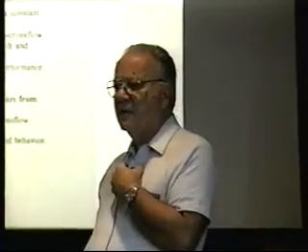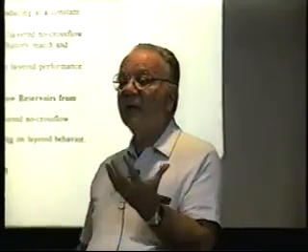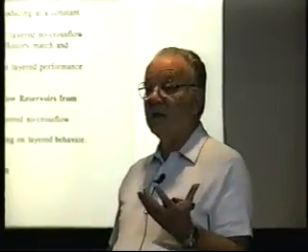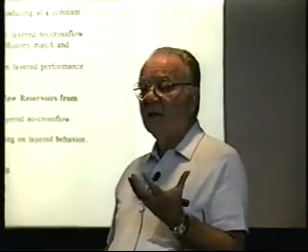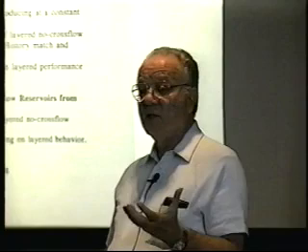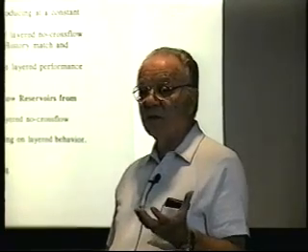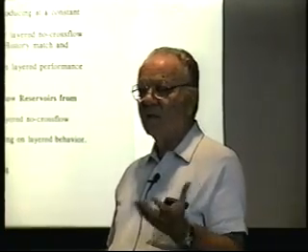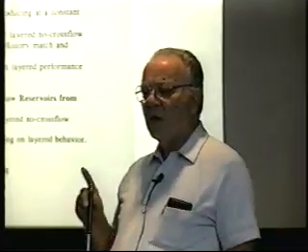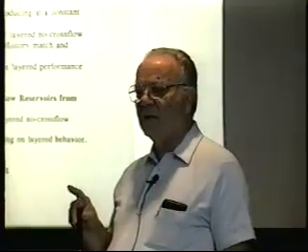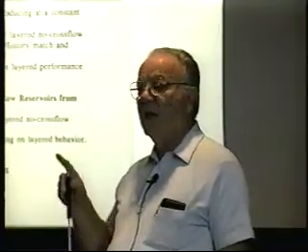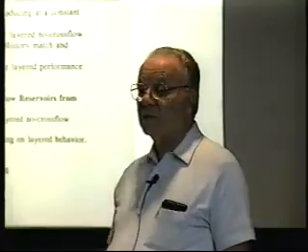There's been a lot of emphasis over the years in pressure transient analysis, but the only application of the numbers that you get is to make a production forecast, or to analyze the data in terms of whether these wells need stimulation, and whether I can increase the production rates as a function of time. So this is what it's all about. And you really will never realize the impact of the data that you're getting from the pressure transient until you take that data and make a production forecast.